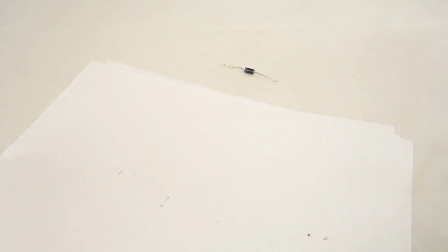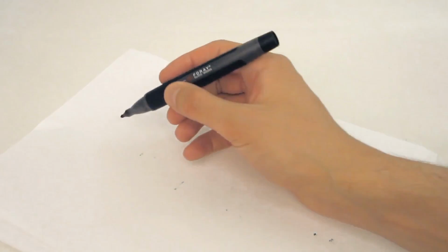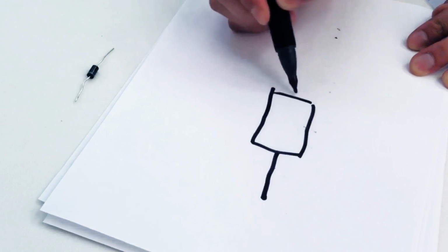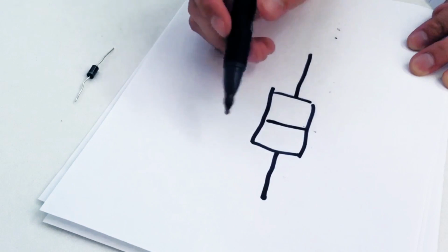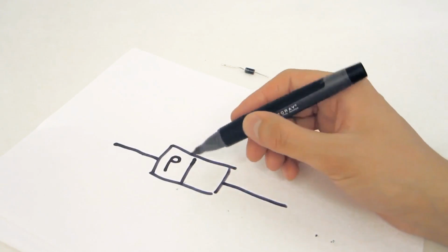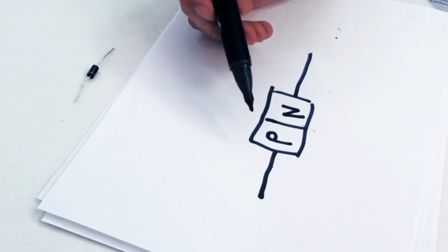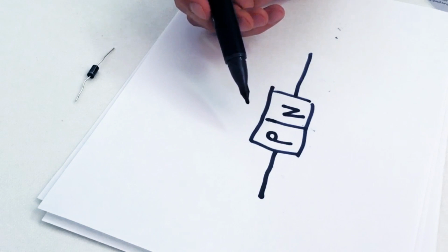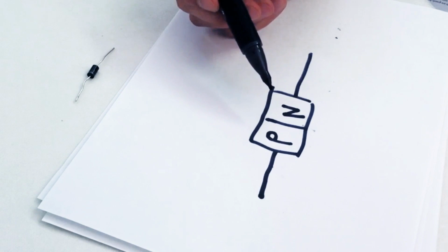The most common type is known as a semiconductor diode. Now, semiconductors are materials that can have the properties of either insulators or conductors. And by mixing the amount of impurity, known as a dopant, we can control the way the semiconductor allows the current to flow. So in the typical semiconductor diode, we have something like this. Now, it's called a PN junction. We have layers of P-type material and N-type material. And with this PN junction, the diodes are given a very high resistance to the flow of current in one direction and a much lower resistance in the other direction.